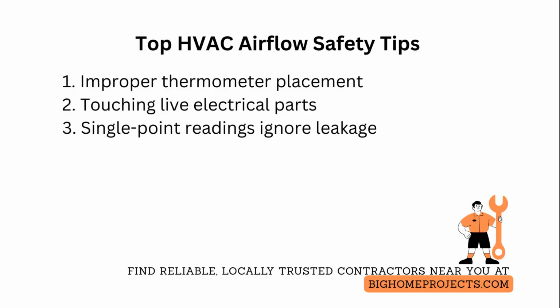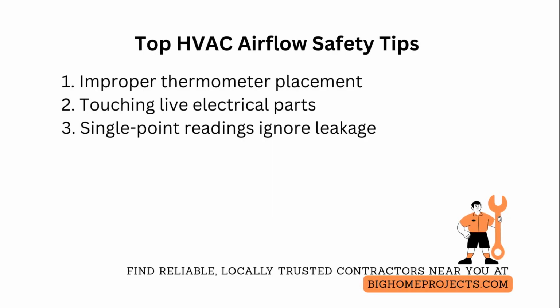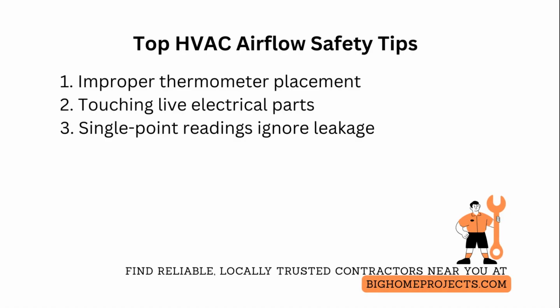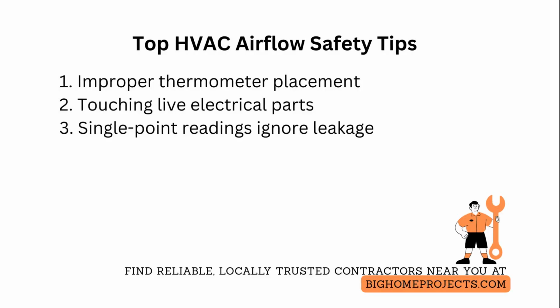One of the other top problems is relying on single-point readings that ignore duct leakage and static pressure, tied to duct leakage testing and static pressure troubleshooting. Correct this by performing a separate duct leakage test, measuring external static pressure, and reconciling register totals with the calculated CFM.